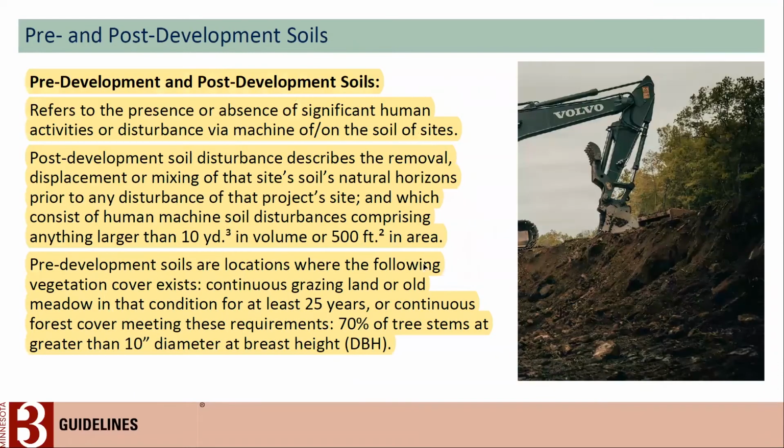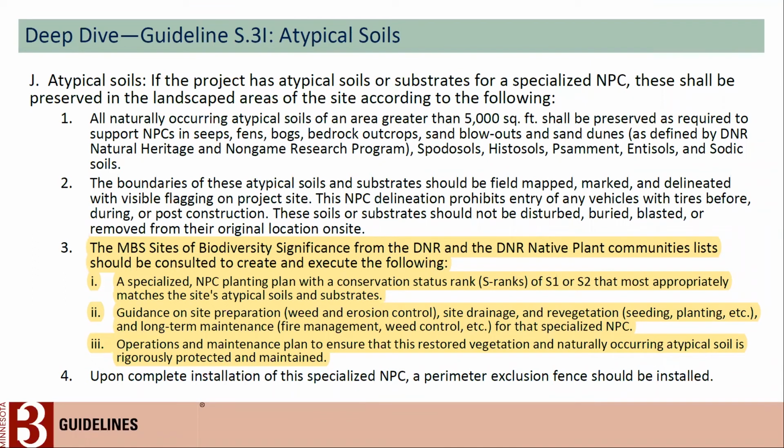I can add that if you're on the web soil survey, you'll be able to find the exact soils mapped for your site. You can use that as a desktop starting point for making a determination about whether atypical soils might be present. Thank you. And this is the National Soil Survey website that you're talking about, the GIS tool. Exactly. That's a good point to make. Thanks, Peter.